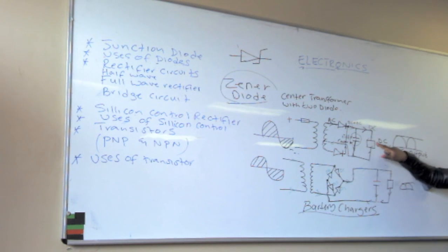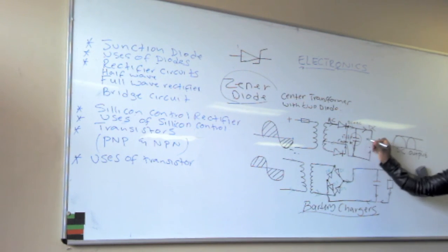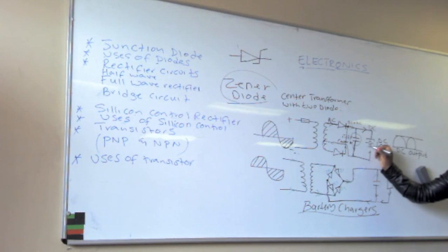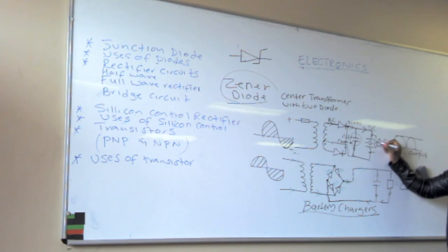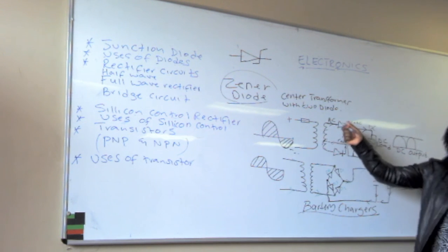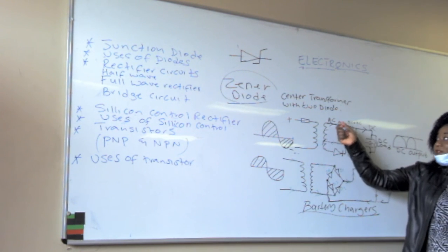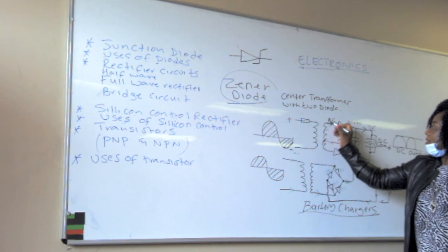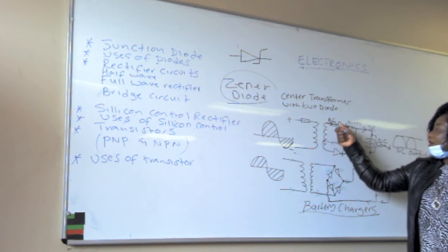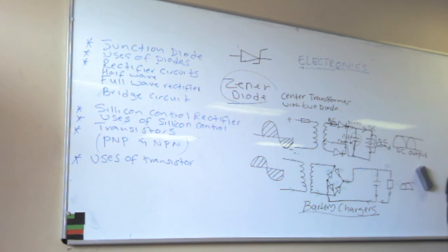What it's telling you is here, you are going to show positive, negative, positive, negative, positive, negative, and then show the voltage across, which is DC volt. It's a battery. It's going to mention, show a fuse also here. If they want a fuse here, you will put a fuse there, or a circuit breaker. Listen to the question. It guides you. On the secondary side, there is a fuse, or there is a circuit breaker. On the primary side, there is also a fuse.